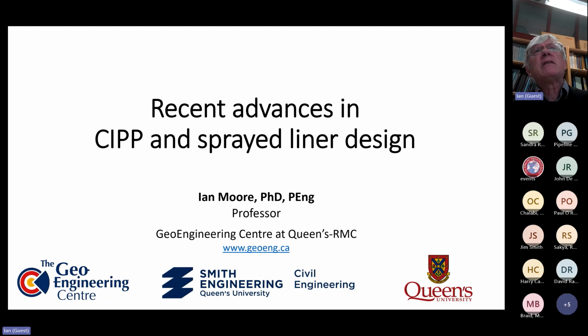Whereas if we're tunneling parallel to those pipes, depending on how that tunneling progresses, is the tunnel face sort of advancing like a wave and producing a ground motion like a wave? So that might produce a fairly severe demand on those joints.